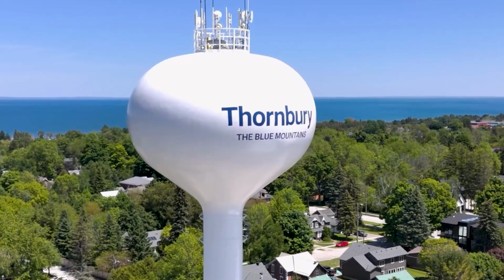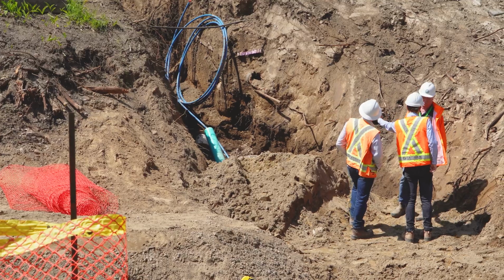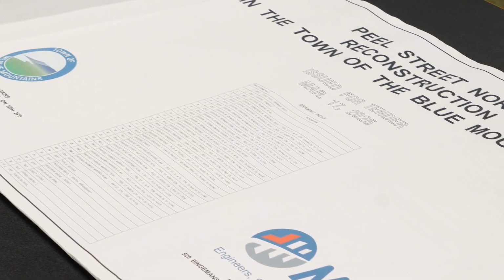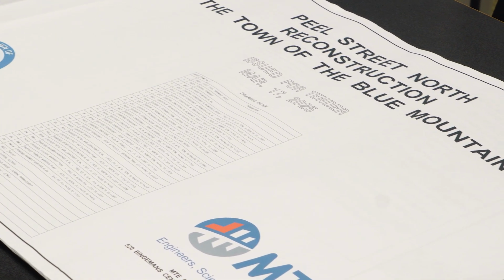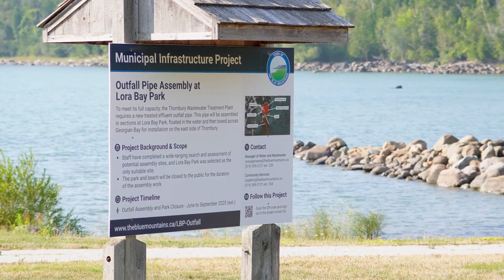A request for proposal, or RFP, is put together by the town's project manager and purchasing division to engage a consulting engineering firm to begin the design process. The RFP will include an outline of all the consultant's deliverables, including any necessary background research, studies, and reports. In addition to the actual design drawings, some examples would include geotechnical investigations and communication plans.